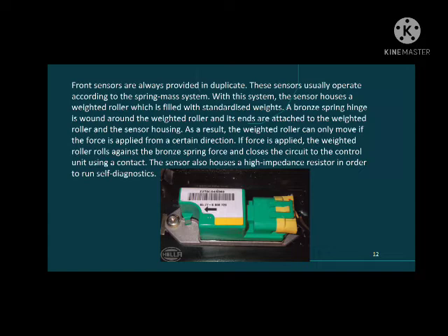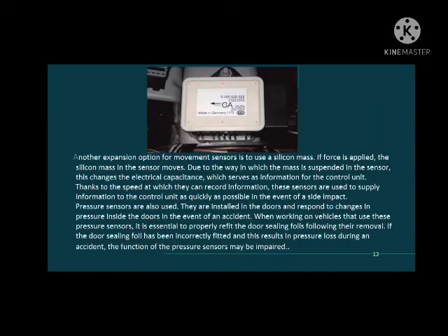The ignition ignites the gas generating material and generates nitrogen gas to inflate the bag. This process from collision to bag inflation should be completed in tens of milliseconds, before the driver's upper body hits the steering wheel.